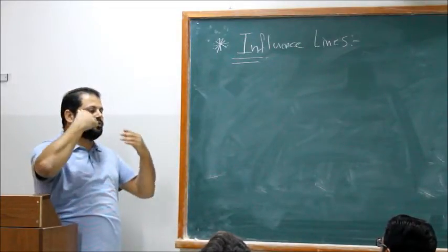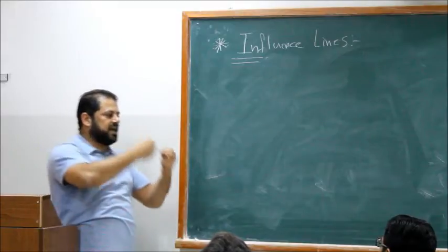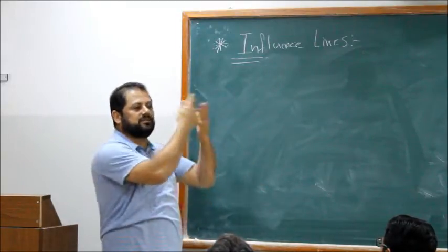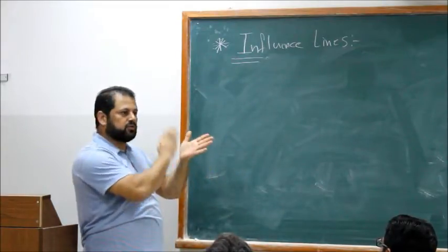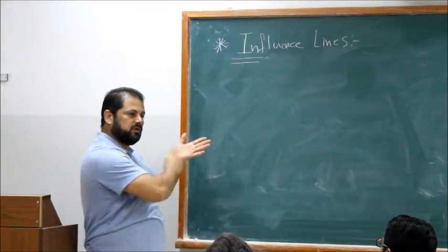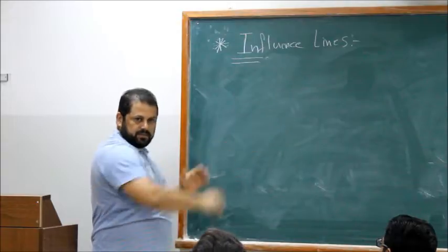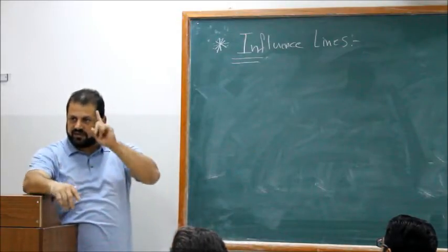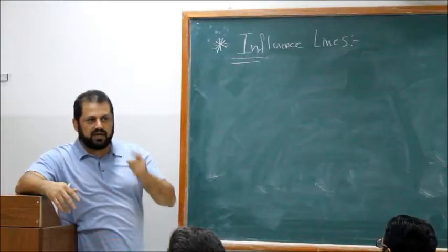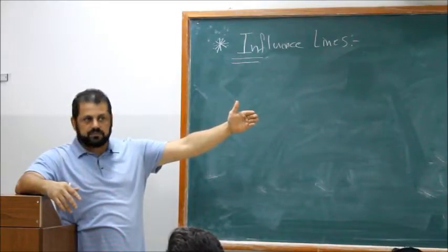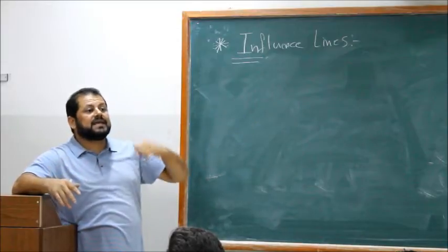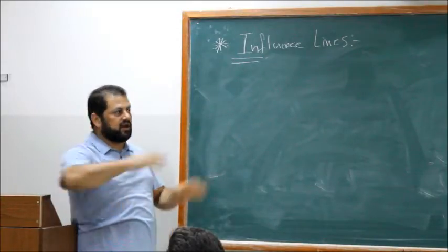Influence line. So in order to find the location of the truck that will give me the maximum reaction or maximum shear or maximum moment, you need to construct the influence line for 1 unit load moving. So the first step is to construct the influence line for 1 unit load that's moving on the beam. Good? Then you place the load to maximize. Then you have the truck.